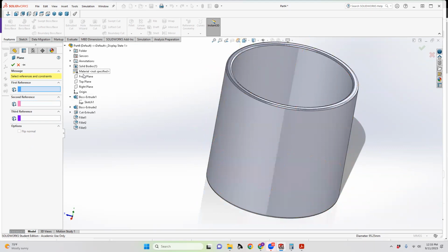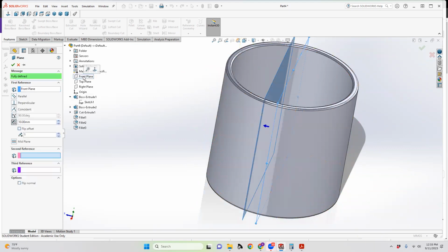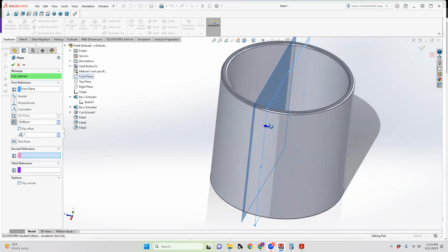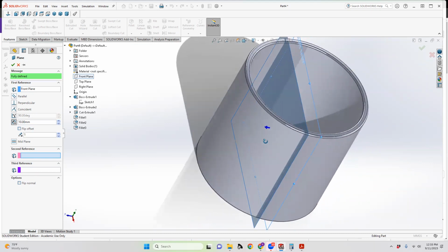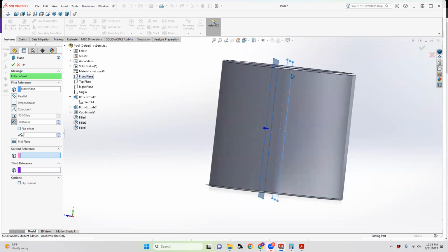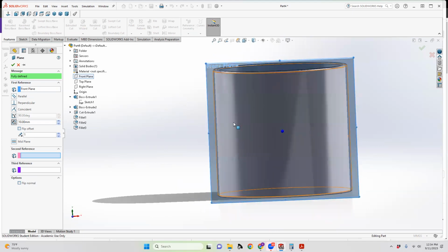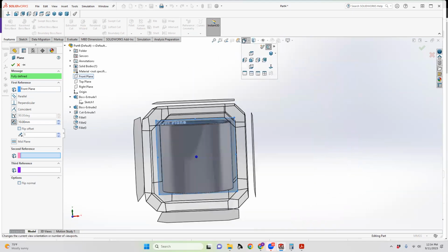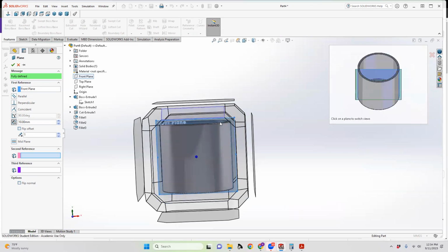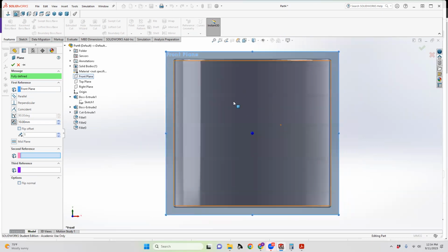What we want to do is reference a perpendicular plane, because if you reference one of the perpendicular planes, you're always going to get essentially what you're looking for. So here, about a 10 millimeter offset from the front plane is going to be good, because we want to extrude a handle from one side to the other. So what we're going to do is sketch this. Again, I'm going to reset to the front plane here, so that everything is square. 10 millimeter offset's totally fine.